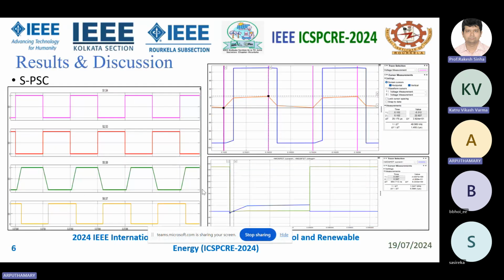Okay, good. How did you design your parasitic elements like primary inductance, secondary inductance, primary capacitance, and secondary capacitance? By using the fundamental harmonic approximation method, I have simulated with the help of K and Q value. I have modeled my resonant components.